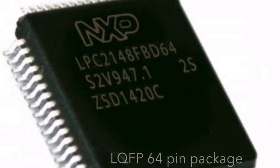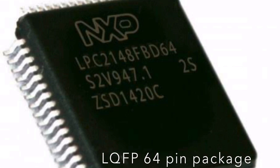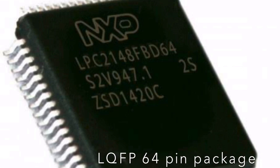Before I go into the features of LPC2148, let me tell you what is LQFP. This is an LQFP 64-pin package, which is a low profile quad flat package. It provides the same benefit as the metric QFP packages. So what is QFP? Quad flat package is a surface mounted integrated circuit package with gull wing leads. Gull wing is nothing but an extension from each of the four sides.